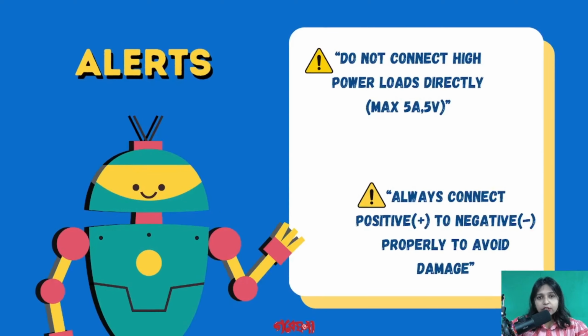Important safety notes: do not connect high power loads directly, max 5 ampere and 5 volt. Always connect positive and negative correctly. If you don't follow this, the components can burn or get damaged.